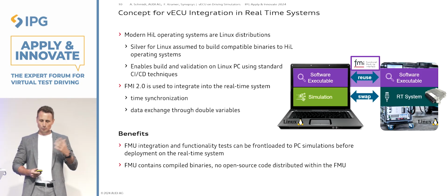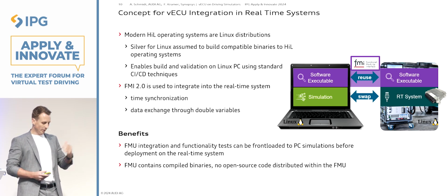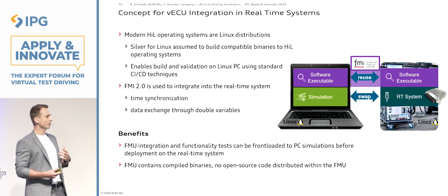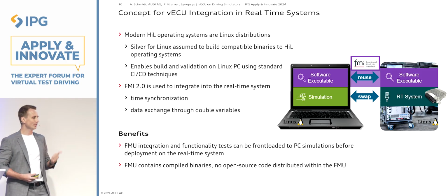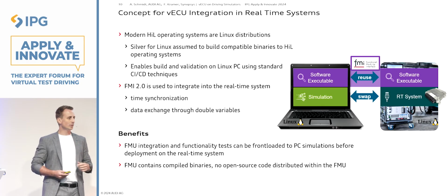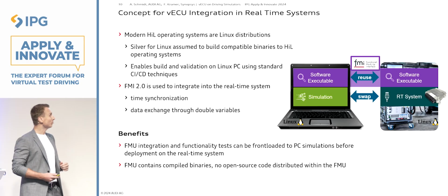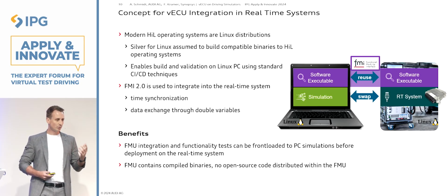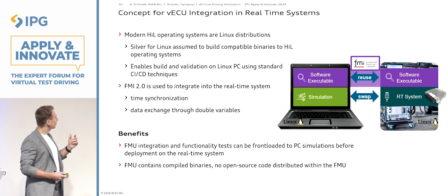The other thing where we are quite lucky is that most modern HIL vendors, IPG by the way, also support FMI, at least 2.0. So we already have an exchange format defined. This goes in the direction of many other talks today: collaboration and standardization. Because of all the efforts in the last years to collaborate in the industry and build standards together, we had a reasonably simple time defining the architecture. So we use FMI to integrate the model, and we are lucky with the operating system that runs on the HIL. What's the benefit of this design?